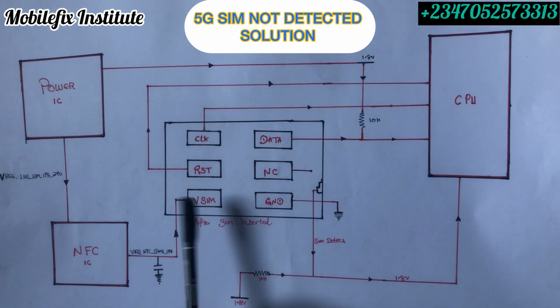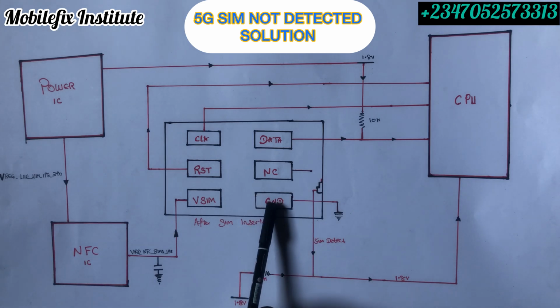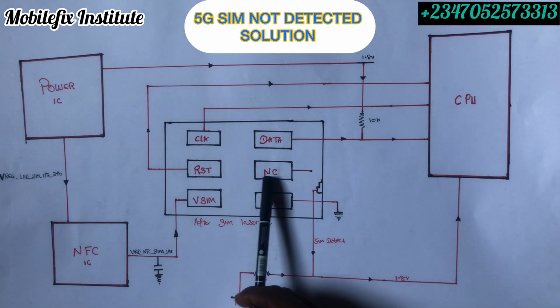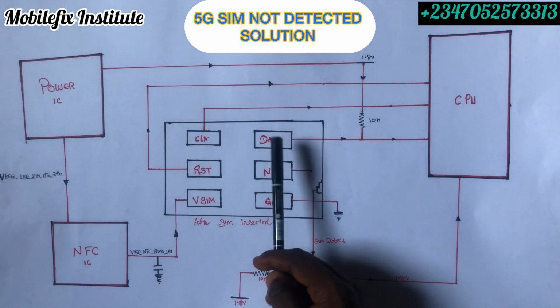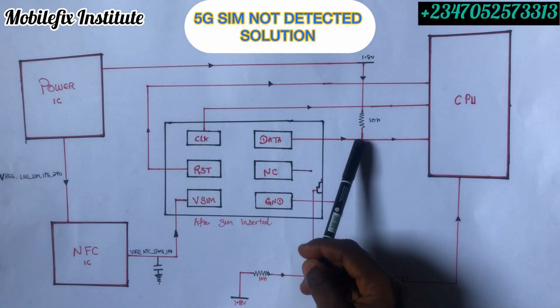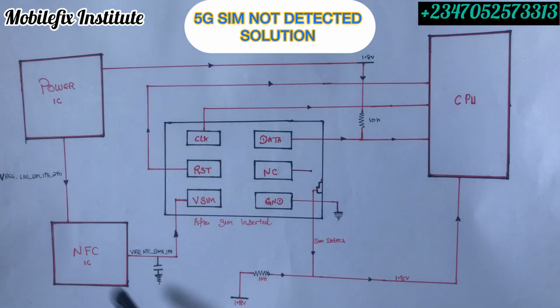This will give you a reading because it's connected to our NFC IC. And then this pin is our ground. It's going to give you a beeping sound. Now this one will give you no readings, OL, because it's NC. Then this is our data pin, which is going to give you a reading because it's connected to our CPU, and it's also connected to our power IC.